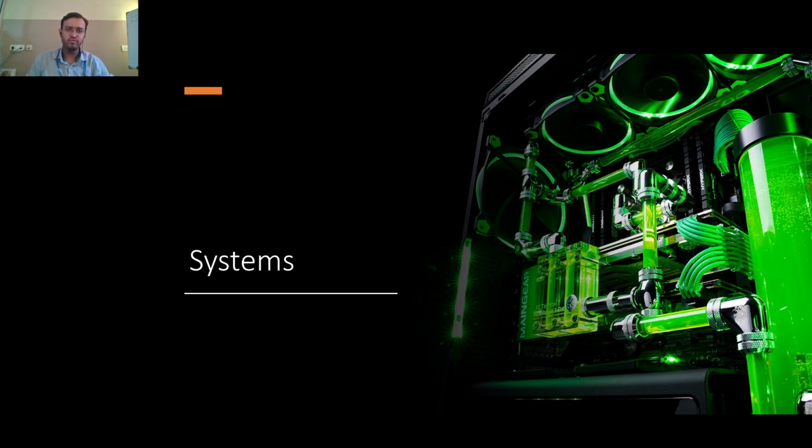So you provide something called a water block, and this is the block which you can see here. The water block is in physical contact with the actual CPU. It's a body of copper which is in physical contact with the CPU, and within this body of copper there are internal pipes through which water flows. As soon as the copper gets hot, the heat is transferred to the water, and the water is carried away through this entire cooling loop.